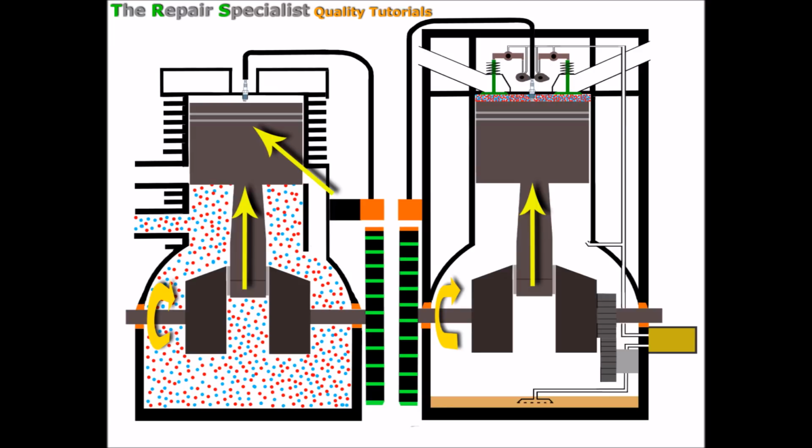Okay, so we'll move over to the two-stroke, and of course the piston's in exactly the same position, but there's nothing up there above. We haven't compressed anything yet. But as the piston rose to top dead centre, it created more of a vacuum beneath it and drew in more of that air and fuel mixture from the inlet port there.